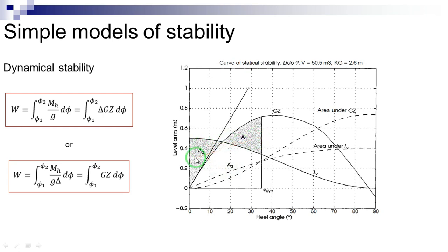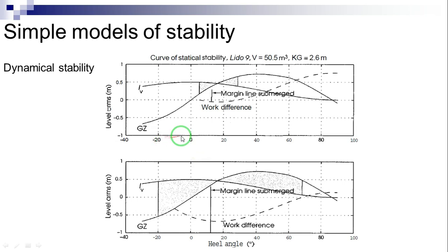In this figure we marked with phi dyne the maximum angle reached by the ship after being subjected to a gust of wind. An elegant way to find this angle is to calculate the areas under the curves as functions of the heel angle phi, plot the resulting curves, and find their points of intersection. In this figure, we assume that the gust of wind appeared when the ship was in an upright condition, i.e. phi equals 0. As shown in the following figure, the situation is less severe if phi is greater than 0 and more dangerous if phi is less than 0.